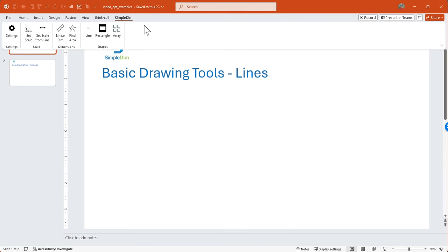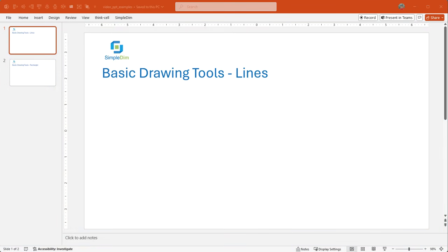And then we're going to go ahead, and we're talking about lines here. What we're going to do is add a line with a specified length and angle. I click the button and it popped the dialog box off screen, so watch out for that. We're going to add a line with a length of, let's call it 550 feet. And we're not going to put any angle on it, though you could. It calculates angle off the plane. So if you want to do angled lines, you certainly can. And here's your line. So that's a scaled line of 550 feet on your slide.